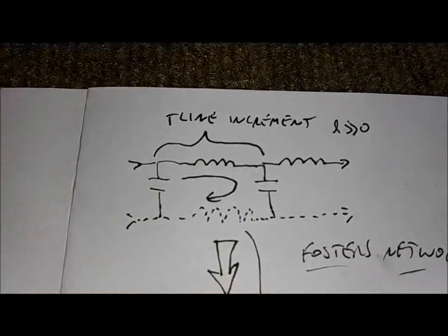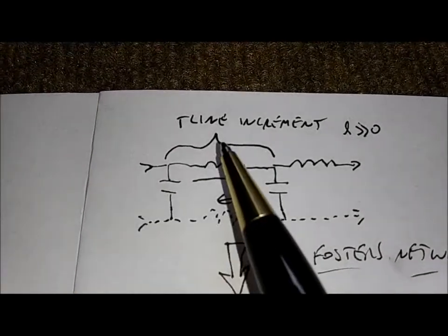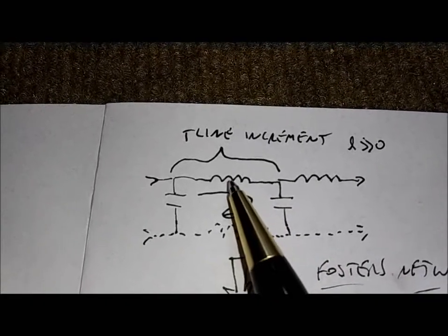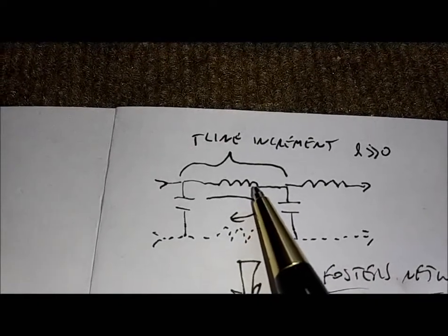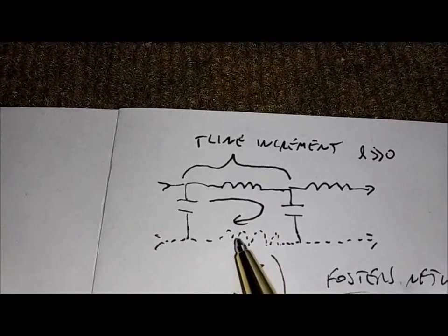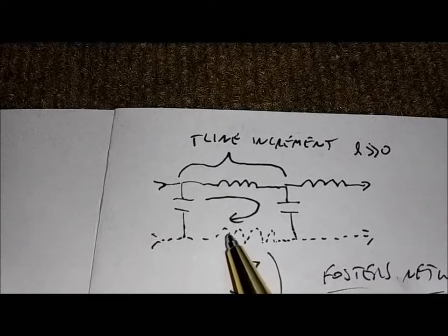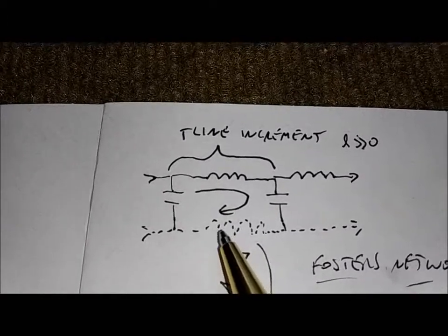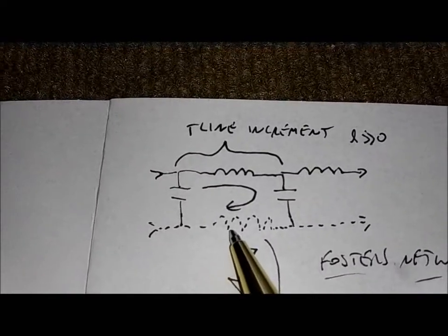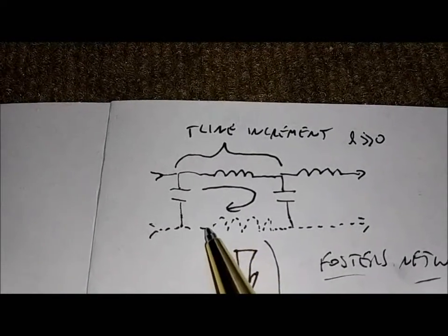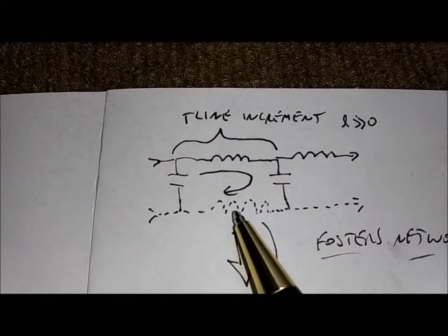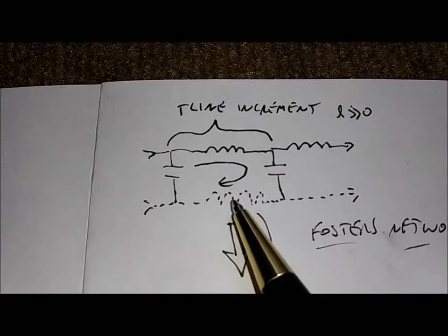2 arrows, much greater than 0. And inductance in series, that's the length of wire, an increment of length of wire in the center conductor, which is also, here's the trick, added in series with the shield inductance, which is why we never put ferrite clamps on a line, because that increases the inductance of that line in a certain area, changes the impedance of that line, and causes an impedance discontinuity and causes an SWR.